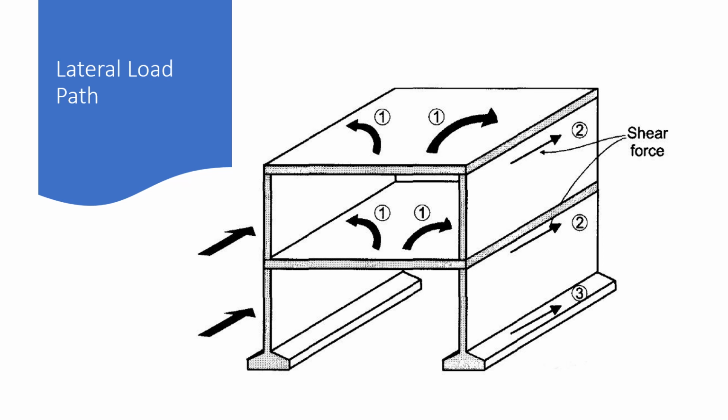Roof and floor systems take horizontal forces from the stories at or above their level and transfer them to walls or frames in the story immediately below. Shear walls and frames are the primary lateral load resisting elements. However, these members also carry gravity loads. Shear walls receive lateral forces from diaphragms and transmit them to the foundations. Foundations form the final link in the load path by collecting the lateral forces from all stories and transmitting them to the ground.